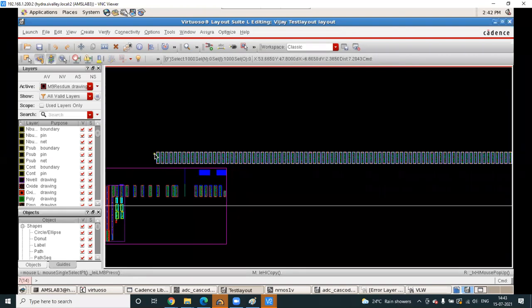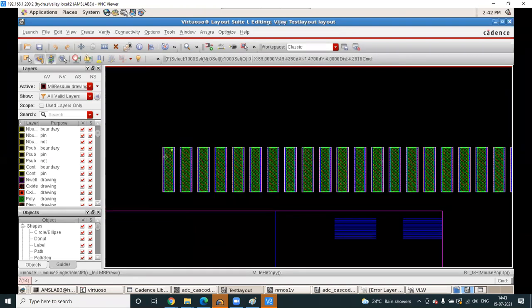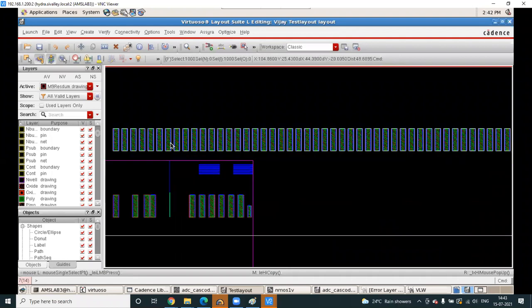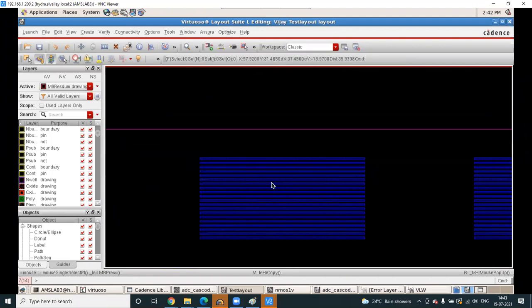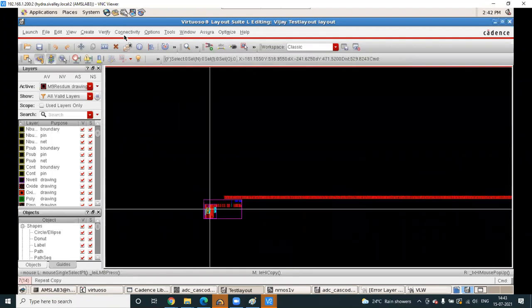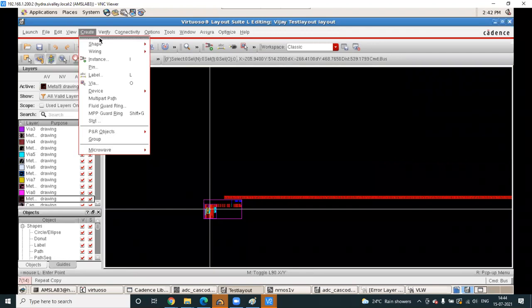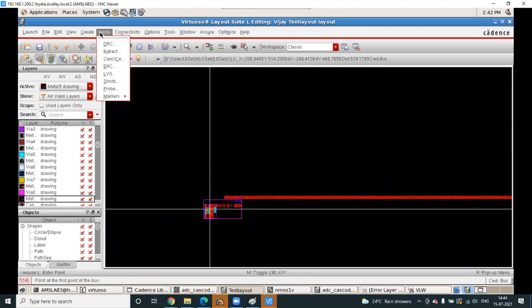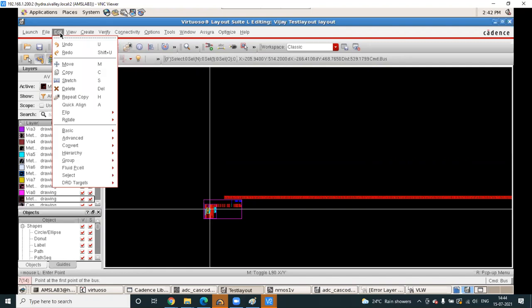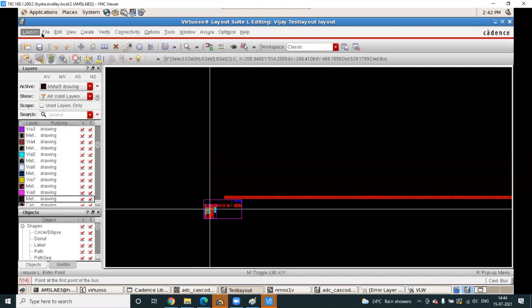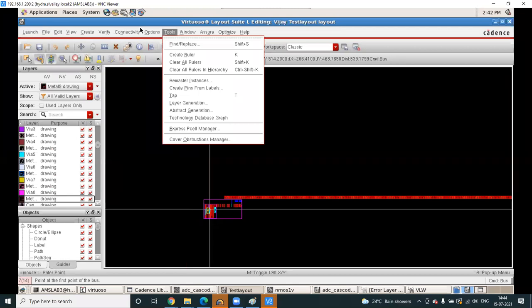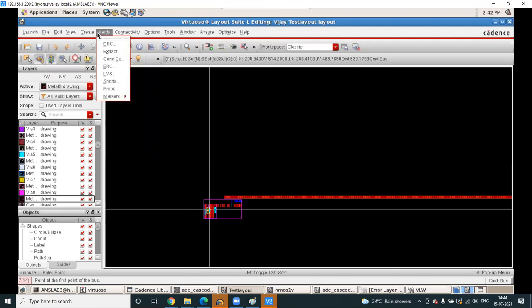There are many tool techniques, meaning layout techniques. Suppose you need to draw 100 connections. There is a bind key, Control Shift X. If I put some bind keys here, you will enjoy it, layout will be done in 5 minutes, even with many blocks. I'll show you once.